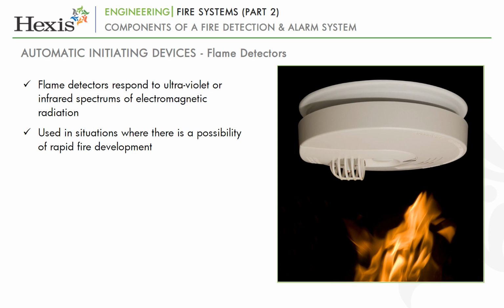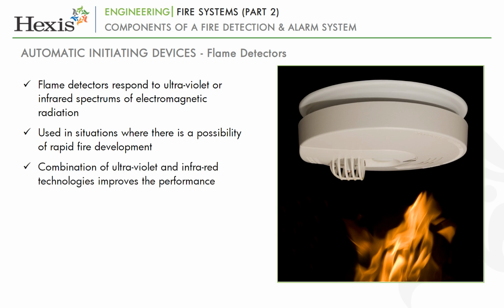flammable liquids. One of the methods to improve the performance of flame detectors and reduce the effect of deceptive phenomena and false alarms has been to combine both ultraviolet and infrared technologies into the one system, or 2 or 3 separate wavelengths in the infrared spectrum.